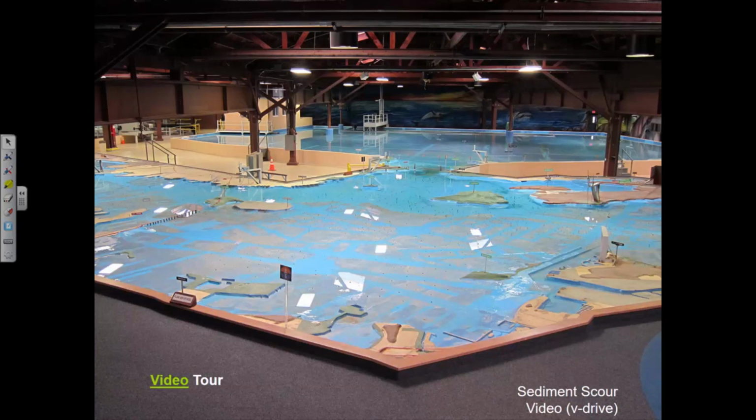Since this is scaled down so small, would they have to use like a lighter fluid to compensate for the... No, that's a good question, and we're going to get into that when you are trying to have what's called dynamic similitude, which is a scaling of the forces rather than a scaling of size. I think since they're continuing to use water, that's why they put in those copper strips, because they needed additional resistance that the fluid itself couldn't provide.